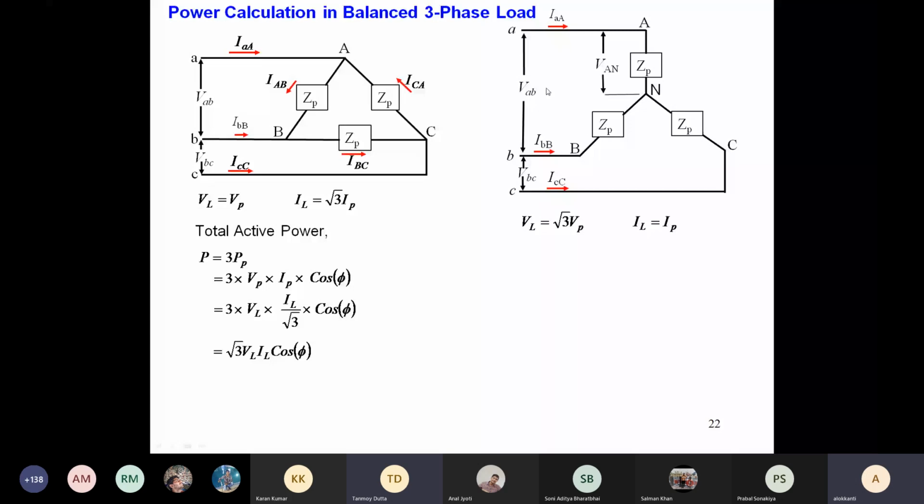No, that is not the confusion. The confusion, I understand, is because you are confusing the load and the generator. But here you exclusively considered the load, and all this addition is basically phasor addition. So this VAB, the line voltage that is getting added, if you break it into components, VAN and VBN, then they will be 1 by root 3 times in magnitude.